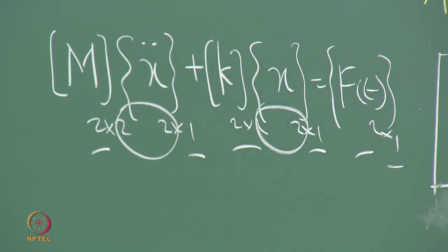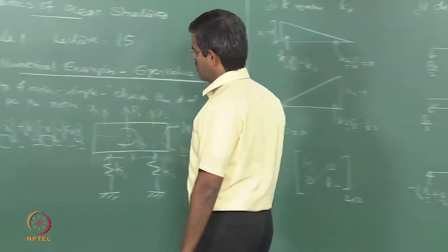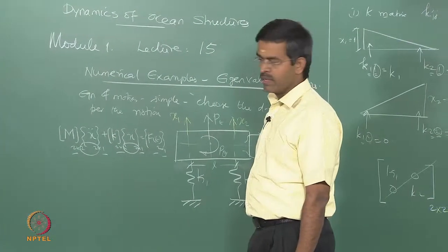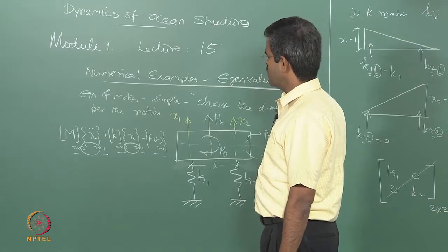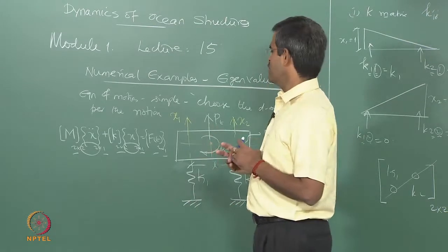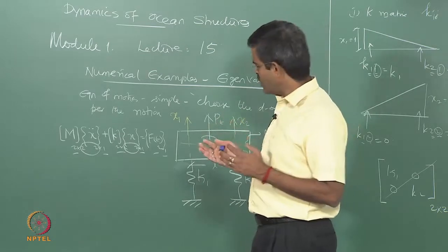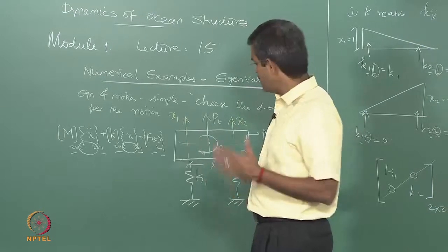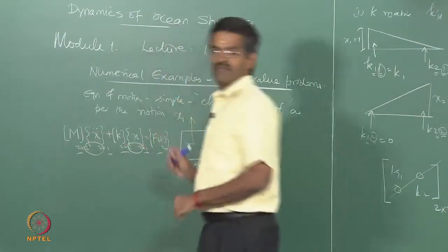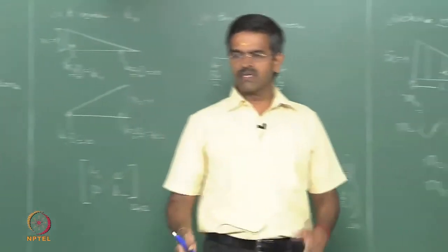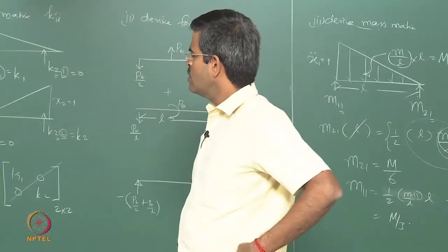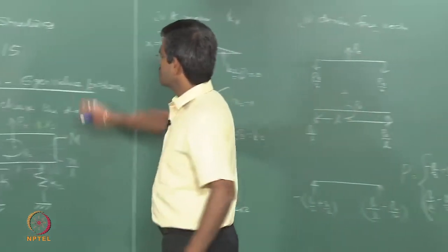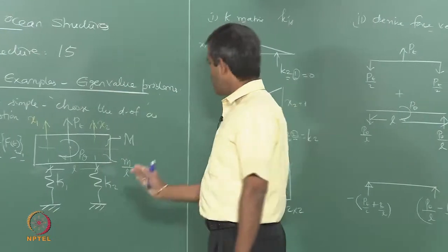We have to now examine how to solve this equation of motion and how to find the essential characteristics of this function like omega and phi, because in the earlier examples being single degree or idealized single degree, we could find omega n very easily, either by finding out equivalent stiffness or by a single stiffness and single mass. But in this case they are all full matrices. So, all the time you will not be able to idealize it as a single degree, you must know how to solve for the natural frequency in the given system, what we now call the classical eigensolver problem. Okay. We will now enter into that.